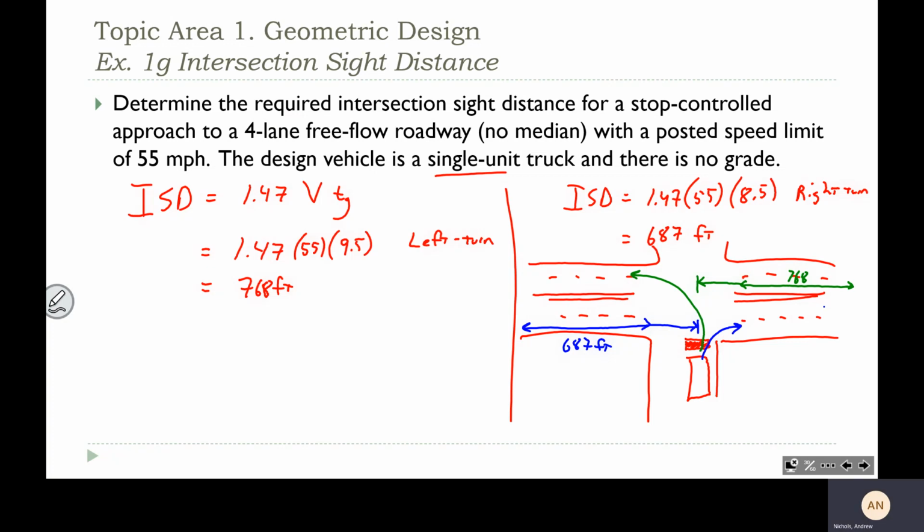And again, the whole purpose of this is if you're constructing a sight triangle, connecting this point back here and this point back here to make sure that there's no obstructions on the roadside. You can also run into issues if you have planters and stuff like that in the median. Those can also block the view for a left turn movement, because if you've got a bunch of shrubs that's wide enough, you've got shrubs down here in the middle. If those are tall enough that they're in that sight triangle, that can create a safety hazard.